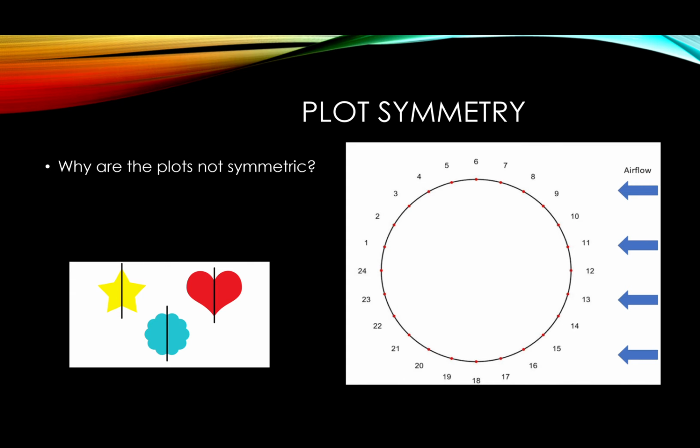When making our code, we decided to make the pressure point at the center of each panel for calculating the pressure. The place this could make the biggest difference is at the stagnation point at the leading edge of the cylinder, where the surface is perpendicular to the flow. We made a large assumption that pressure point 12 was the stagnation pressure. This would mean in order to get symmetric graphs, pressure point 12 would have to be perfectly oriented perpendicular to the flow. And that assumption was incorrect. Upon looking at our data, it appears that pressure point 13 was actually the closest to the stagnation point, as the coefficient of pressure jumps up at that point, suggesting that's the stagnation point.